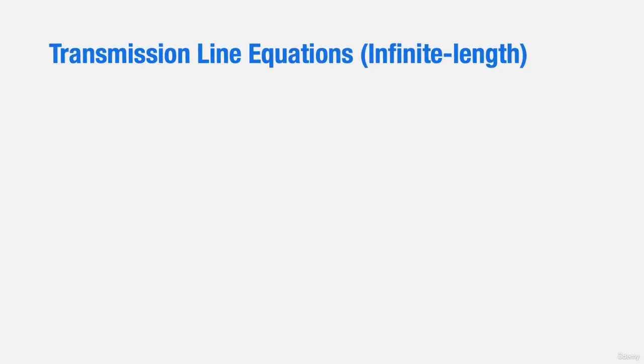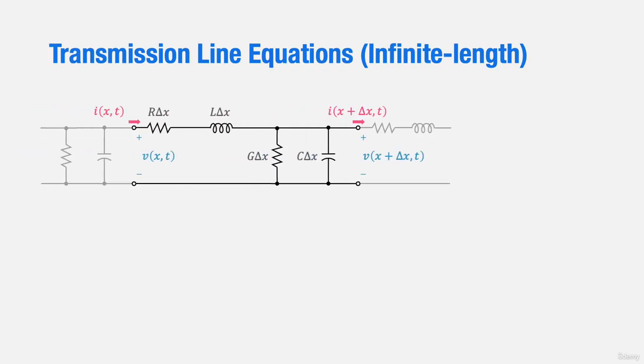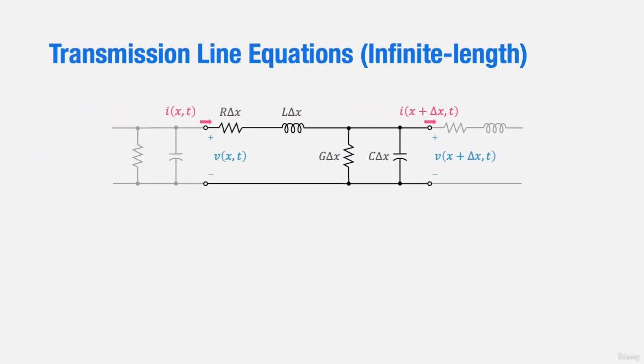Okay, you might be wondering how a transmission line can be infinite in length. In the real world, it must be of finite length. However, for the sake of simplicity, we start with an infinite transmission line. This approach is useful because with an infinite line, its structure is uniform everywhere, which simplifies the analysis. We can arbitrarily cut a small piece out of it to analyze its properties.